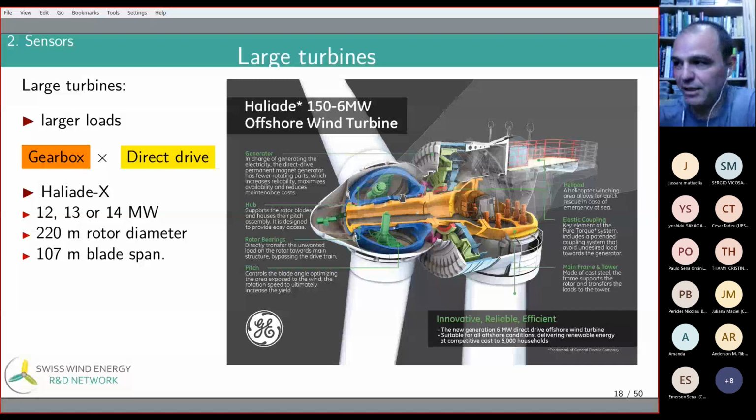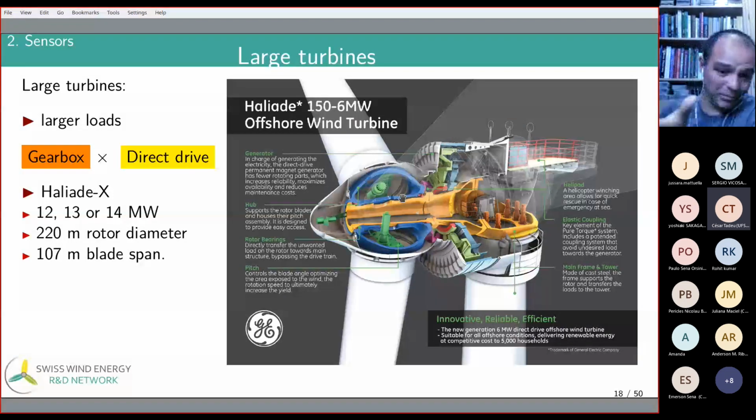Okay, I understood. If the sensor reads an incorrect signal, they send an incorrect signal to the actuator, hydraulic actuator or electric motor, to control a wrong angle for the pitch control. So then you have a faulty pitch control. Yeah, I get it.